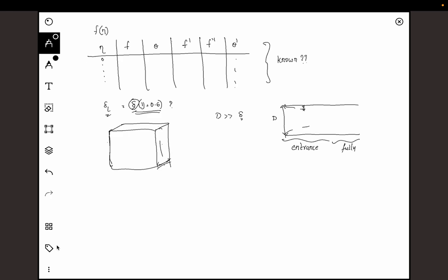So if the walls are very close to each other, such that delta is of the same order of magnitude as the separation between the walls, then both boundary layers will interact with each other. Then some new flow physics would be developing there. But if they are sufficiently far apart, such that the distance between them is way higher than the boundary layer thickness, then you can safely assume both of them to be two separate flat plates, and you can use whatever correlations we are developing here.